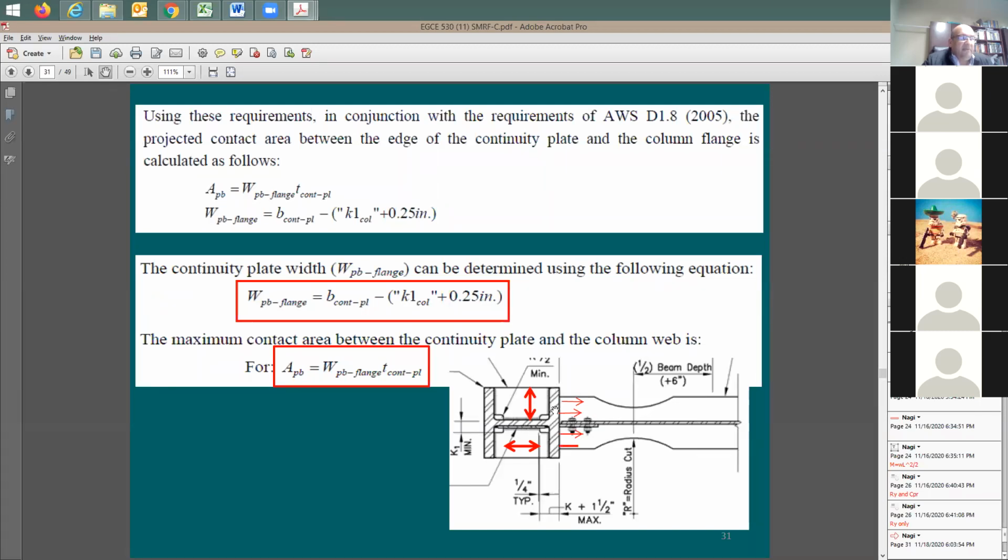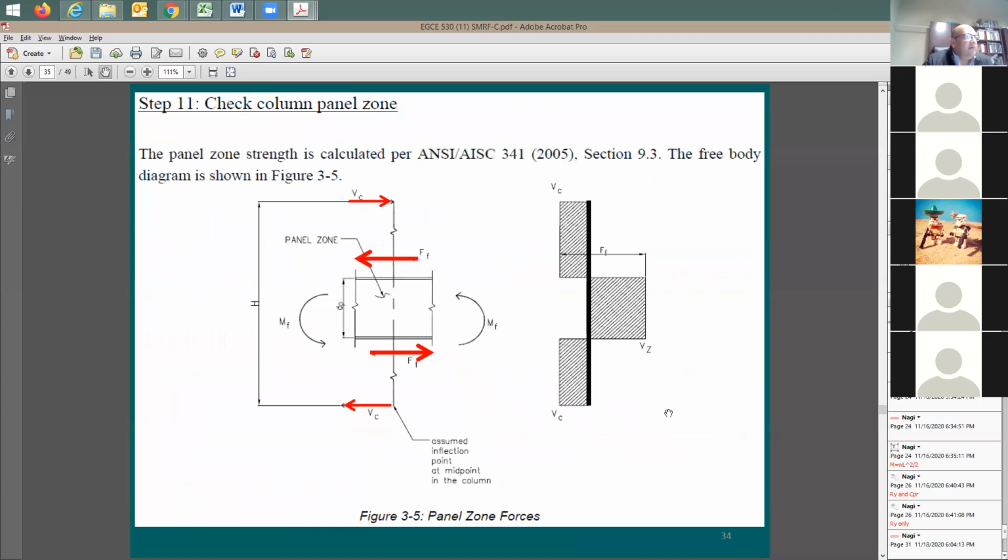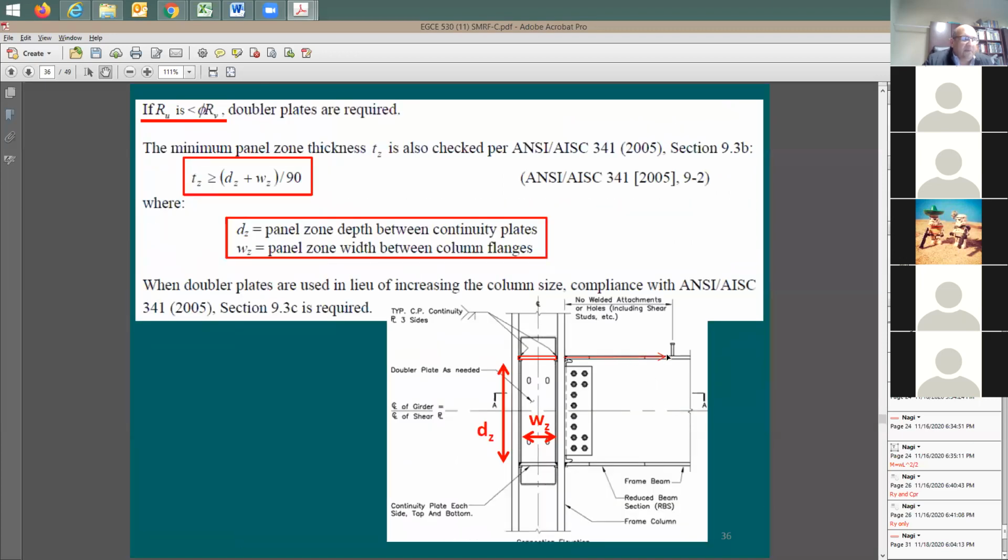Now, if this flange is going to start to be pulled this way, I'm expecting that maybe the flange is going to be doing this, right? It's going to be bent this direction. And from this side, it's going to be also bent this direction, which is not good, right? So I'm going to see some trouble here. So the best way, right, instead of putting bending on this flange, now I'd like to bring this force all the way to the web, right? So the conclusion, if you have any shear or any tension, I'm going to go back here and say, if you put here any tension, you'd like to transfer it to the web of the column. So you'd like to engage this flange and bring the entire force to the web of the column.